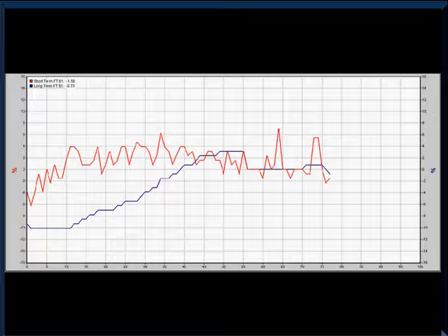To really say what happened here is, we just got through fogging the intake and cleaning the injectors on a car that had excessively high long-term fuel trim. When we're looking back at this zero we're at now, it's telling us we have fixed our dirty fuel injectors, corrected our long-term fuel trim. We like to see long-term below 5%, but really get upset when it gets anywhere around 10%.